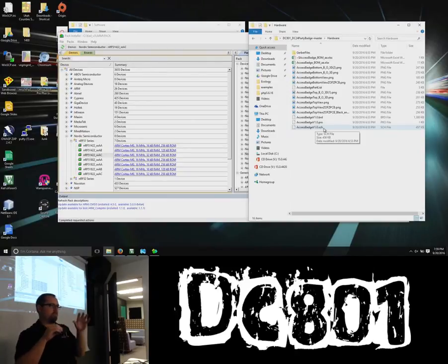So that shows this pin goes to this thing. So if you want to verify for the H file that you're connecting your pins to the right GPIO pin on your device, you verify in your schematic. This way, when you print it, you know that this goes there. If you have issues on your schematic, then you have issues with your program. So it's a good way to validate your program, make sure that you're really calling what you thought you were. Because if it's not lining up how you thought, then you're either calling the wrong pin, you have to verify in your schematic, or you missed your H file, and your H file is listing the wrong thing.